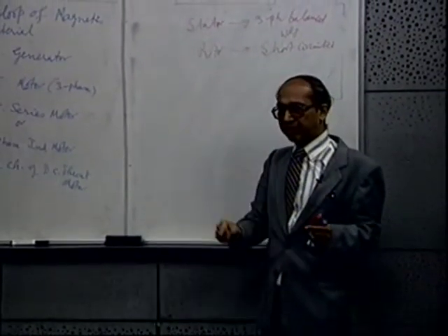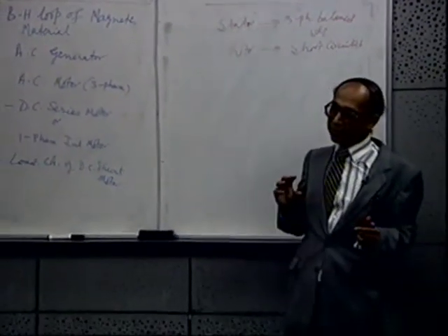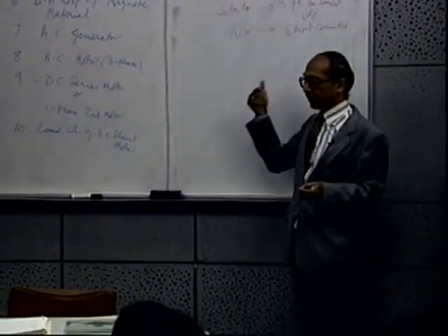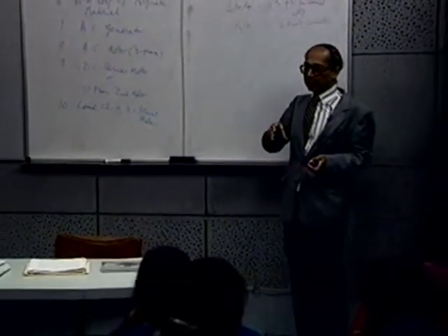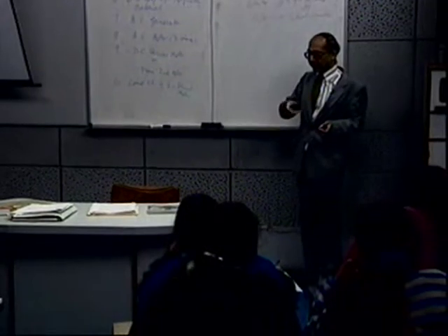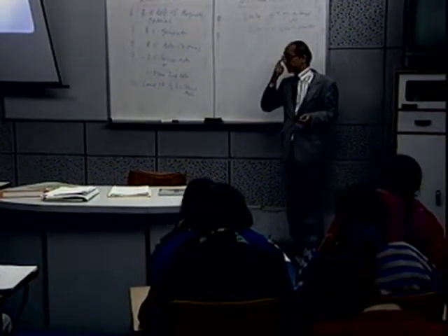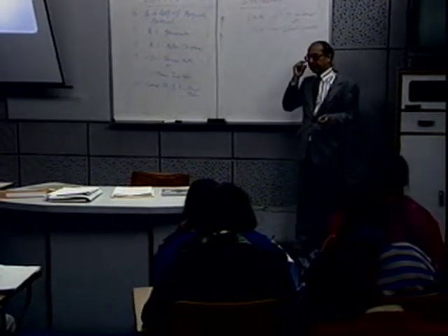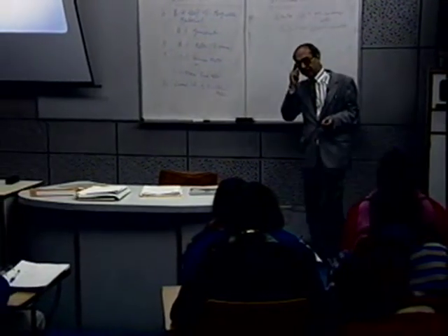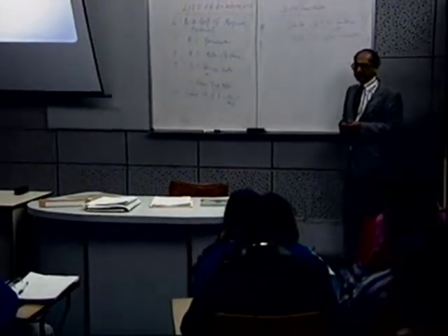Whenever there is a rotating magnetic field in the air gap, there is an induced current in the rotor because it is short circuited, like a transformer. So the rotor tries to align with the stator field, and it starts catching up and rotates. This is one of the inventions of Tesla, invented in 1886 or so, the three-phase induction motor.